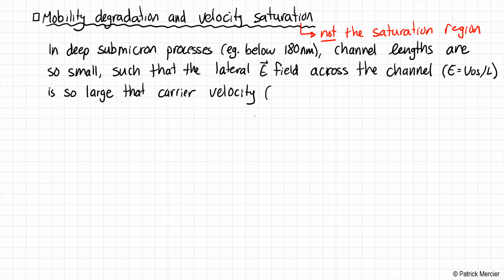I'm going to attempt to use a lowercase v. I'll put a little doodad on the end of the v here and make it a little smaller than my uppercase V's to distinguish between voltage and velocity. Again, please try to be as clear as possible when you do your writing in this context. The velocity, which is given by the mobility times the electric field, ceases to increase linearly with voltage.